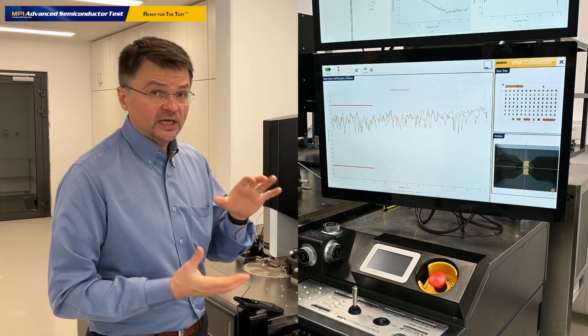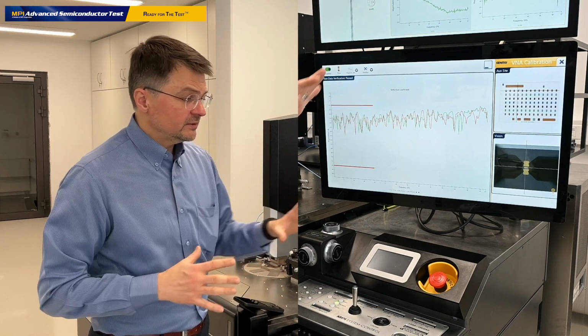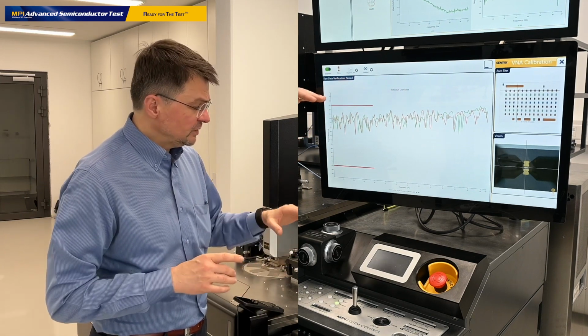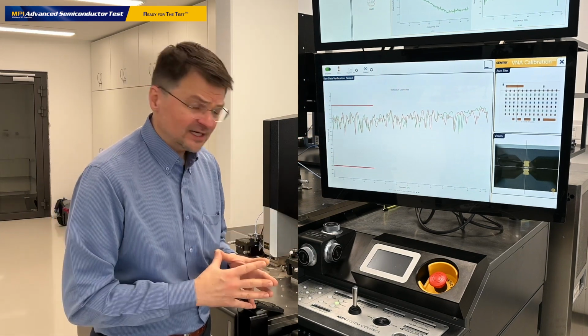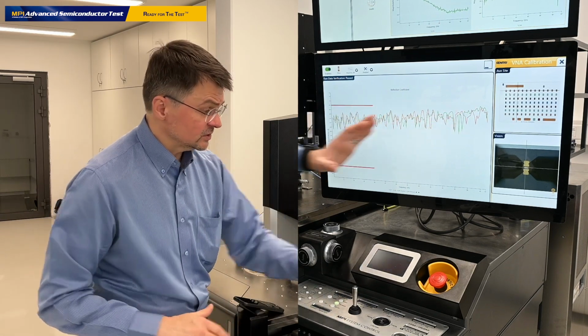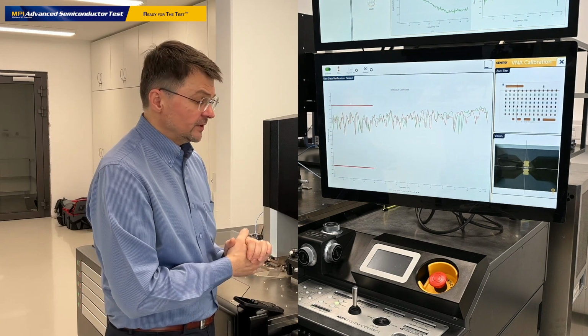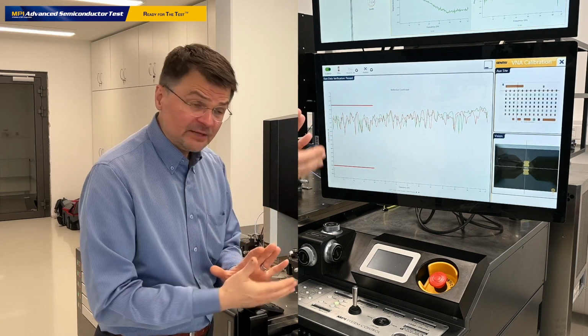So we assume that for this particular system, or this configuration, the return loss of the through standard should be slightly better than negative 20 dB at the low frequency range. And our measured data here for S11 and S22 are within these boundary ranges. So the boundary can be adjusted at any time.